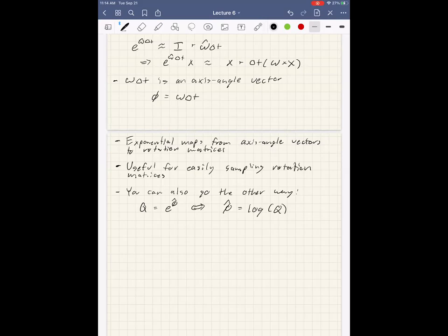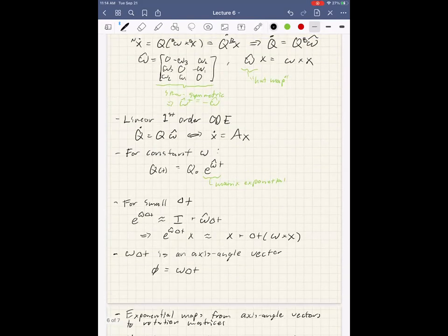Turns out gyros are actually extremely good if you spend some money on them. They have very, very low noise. They have bias, which is a different thing. But their noise in terms of angle random walk and stuff, if you get a high-end gyro like a ring laser gyro, they're fantastically good. So you can really just plug into this ODE. I mean, yeah, you can take a modulo.